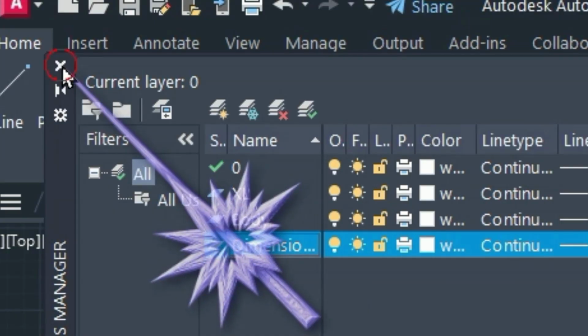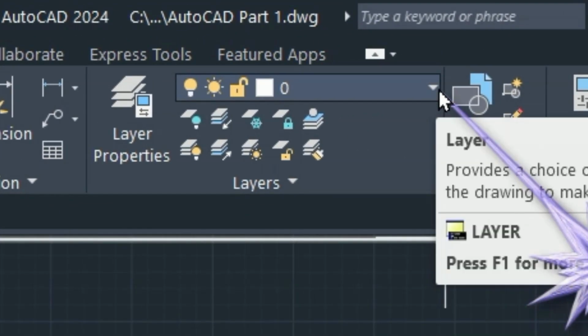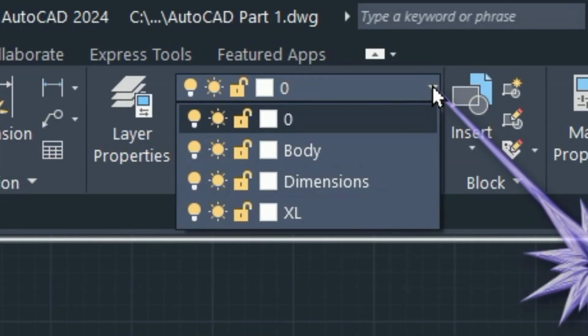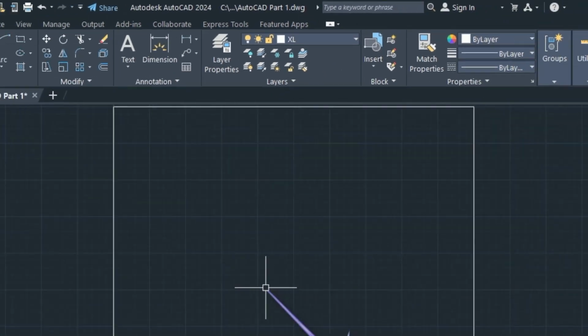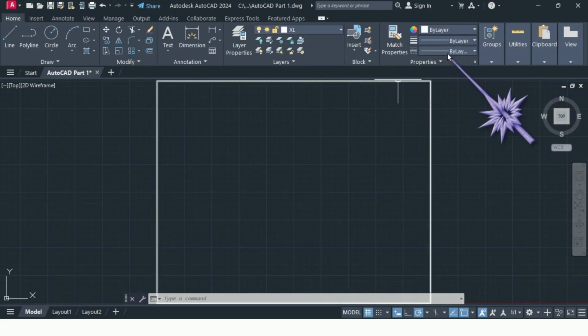I'll close it here. Then come back and make the construction line layer the current layer. You open here, you always open here, this XL construction line. So you're going to draw construction lines. We'll come into that later, but we're just starting. I'm just introducing it. Meanwhile, as a beginner, you can still leave all these ones.